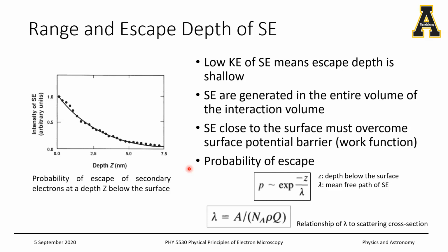Okay, so now we know that the backscattered electrons are ones that travel at high velocity. They approach the nucleus, and then they are deflected from the force field without the loss of any energy or momentum. There's just a change in the angle of the electrons, right? And this can happen over a significantly large volume of the interaction volume, right? So if you remember the image that I showed about 2 or 3 classes ago of the depth profile of the various processes in the interaction volume, you will find that the backscattered electrons probably penetrate somewhere between a few hundred nanometers to a couple of microns.